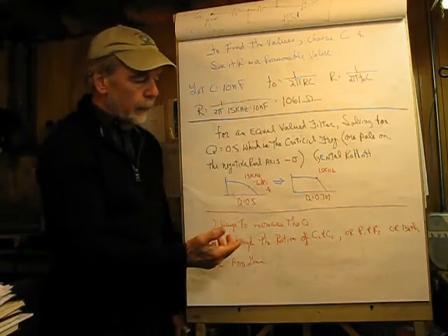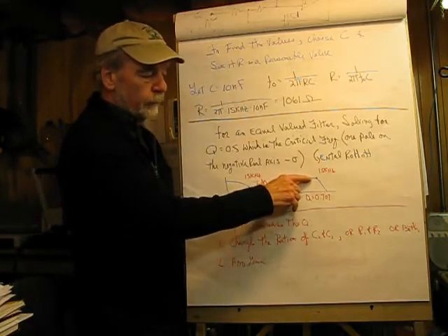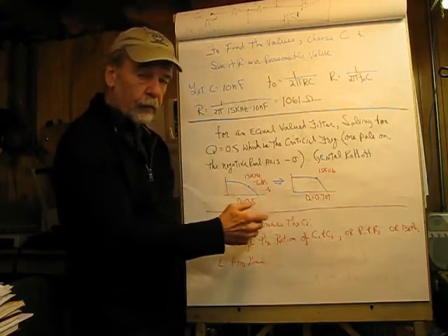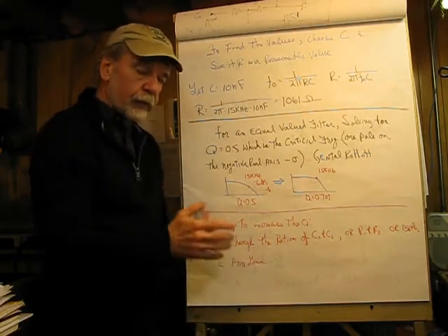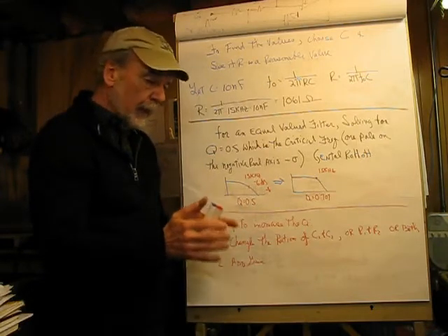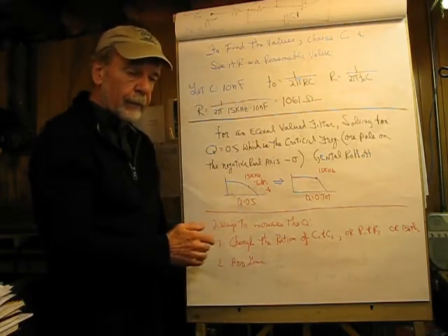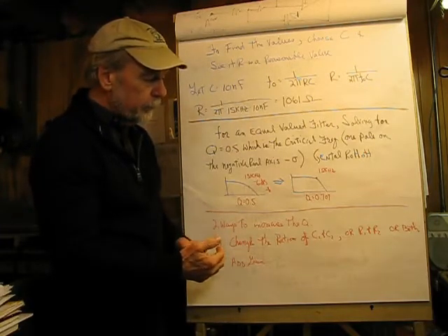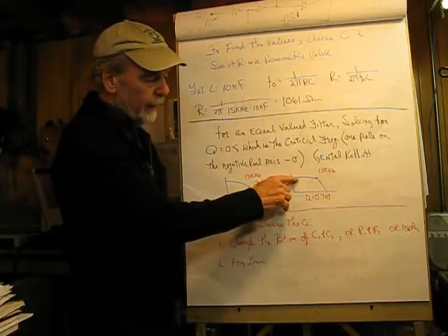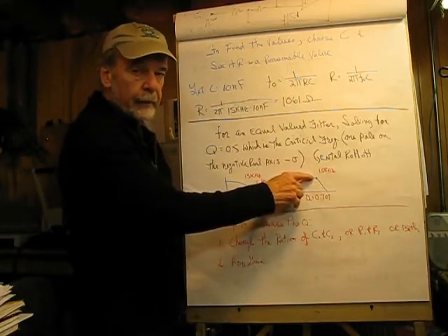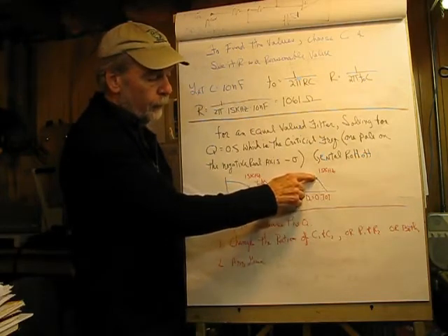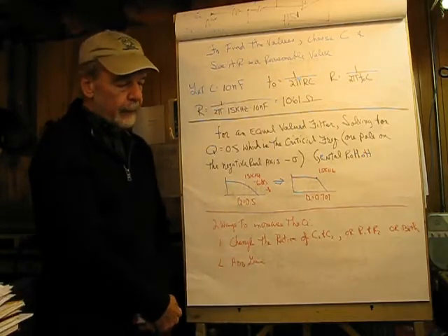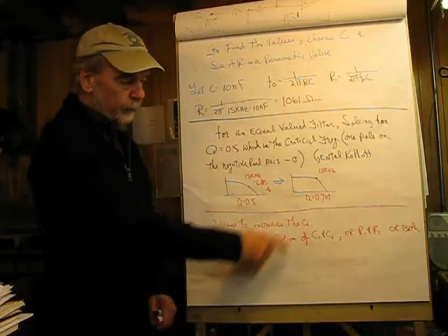For example, a Bessel function doesn't have quite the flatness of this, but it has a very nice phase response, called group delay, where the high frequency components of the signal are delayed about the same as the low frequency components, and in certain applications that's very important. And a Chebyshev has feedback such that you have little ripples in the passband, and that's the cost of it, but when you get to the corner frequency, it immediately dives into a negative 40 dB per decade roll-off, and that filter would have a higher Q than this circuit.